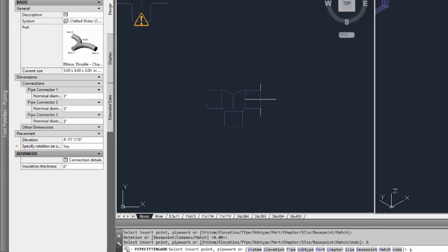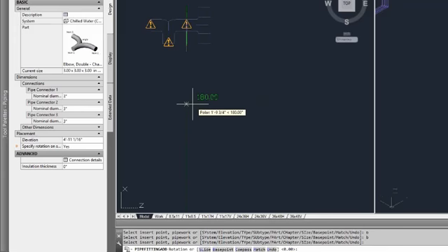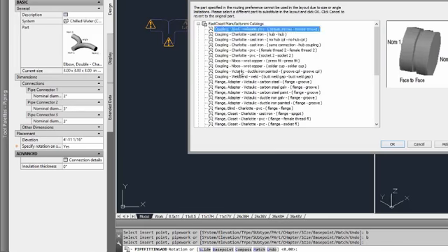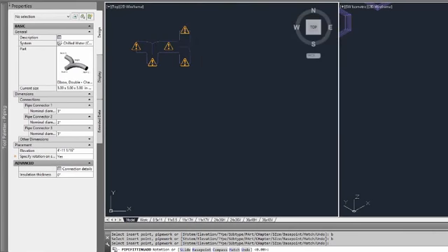So I hit it twice. I can now place it right there. Then I can come in here and place it on the fitting like so. And it's going to try to find a coupling. And so I'm just going to place in a no hub coupling for it, like that.